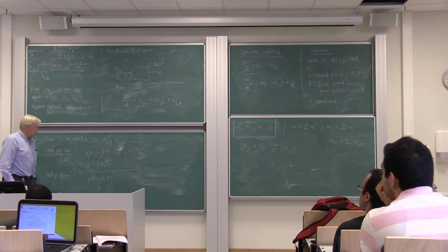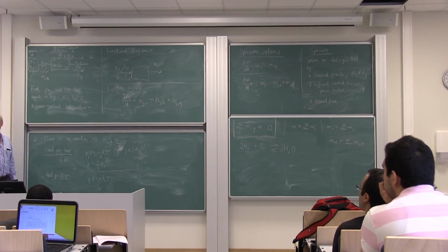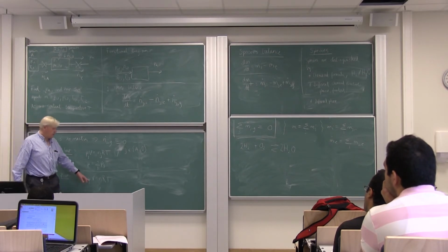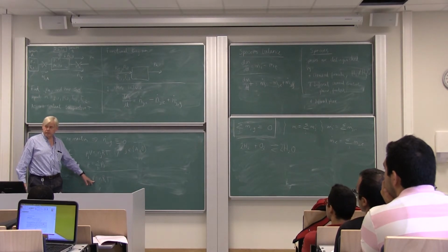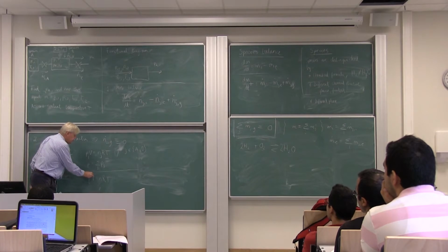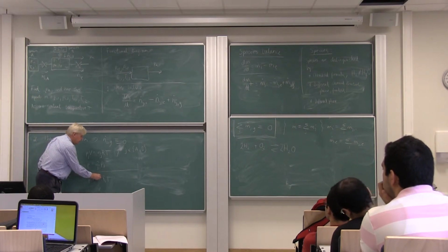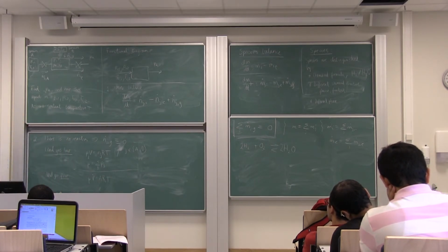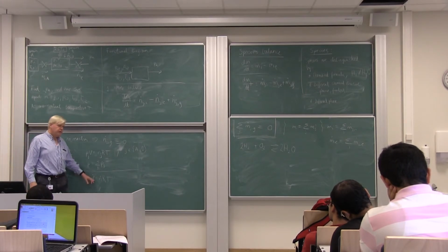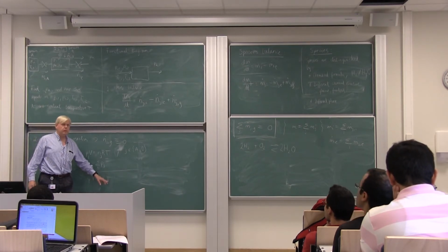If I should turn this into a flow form, what are the extensive variables? Is P an extensive variable? P is intensive. What about V, volume? Extensive, so we can use a dot on that, so flow. What about N? N is extensive, so we can have a dot on that, and then R and T. So this is a flow form of the ideal gas law. Pressure multiplied by volumetric flow rate is equal to molar flow rate multiplied by gas constant multiplied by temperature.